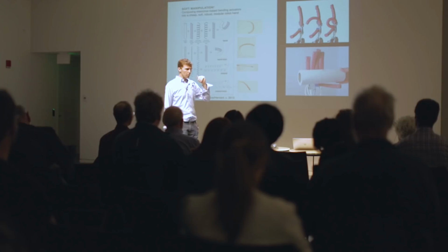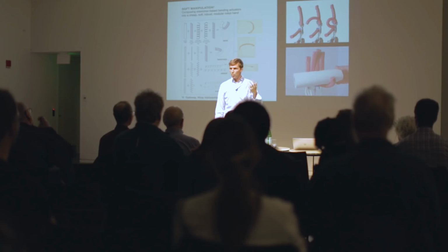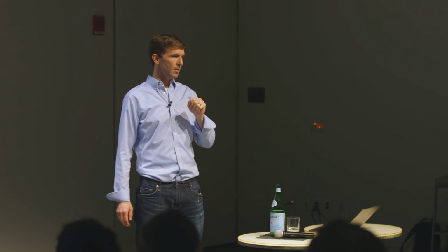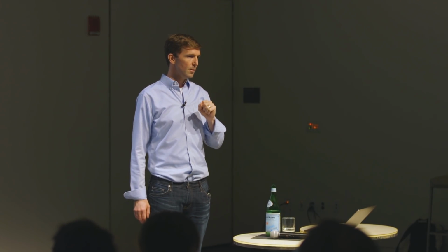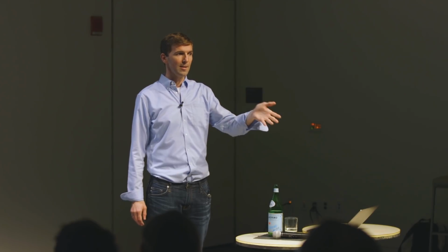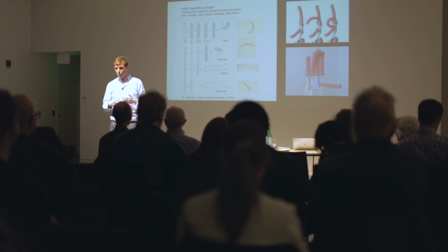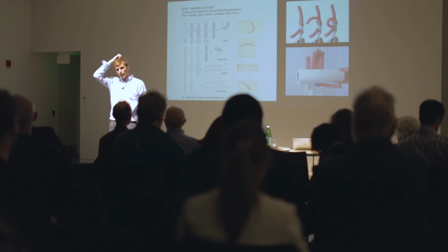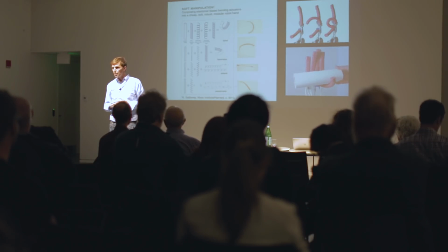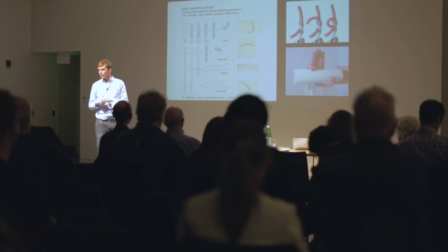So that's a typical and extremely successful automation example of robotics. But what do you not see in that vision? You don't see humans. You don't see anything soft. You don't see anything delicate near them because they're dangerous, right? In fact, you see cages around them such that they're not going to harm anything or anyone. So the motivation for soft robots is to get away from that, to make robots that are impedance matched to natural systems, to humans. We have some efforts in wearable robotics. There's a lot of effort led at the Wyss Institute by Connor Walsh in wearable assistive devices. That's one application area, and it gives you the flavor of soft robotics.